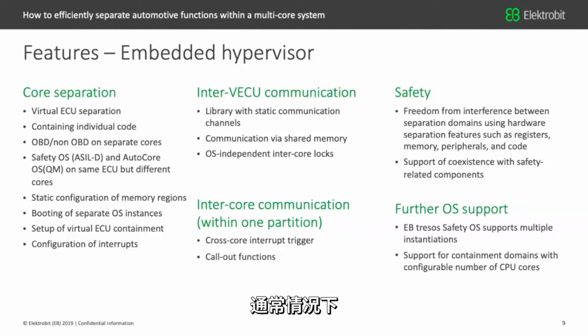Usually the timeline for the OBD features is a bit more difficult, since there are legislative parties involved to get approval on release of certain software parts. With the embedded hypervisor, we think it is a valid argumentation that there is no interference between those two ECUs, so one can be released and not be touched, while the non-OBD part might still be changed in one or the other way.